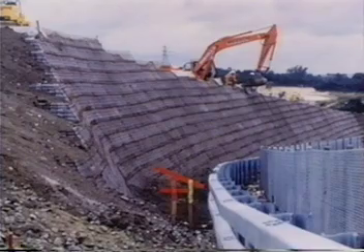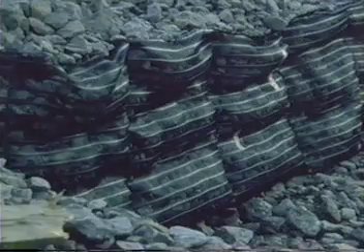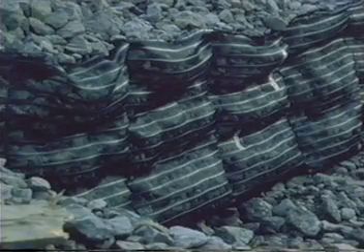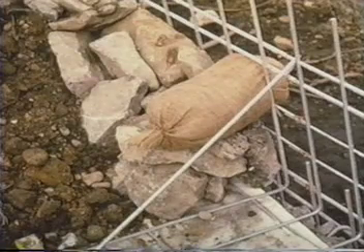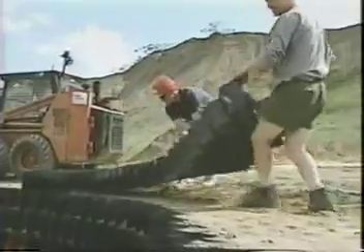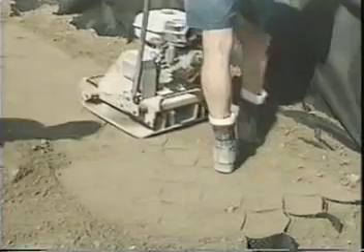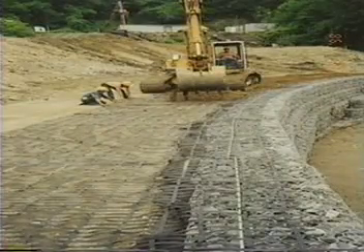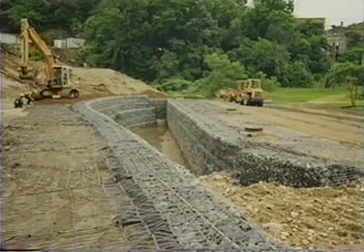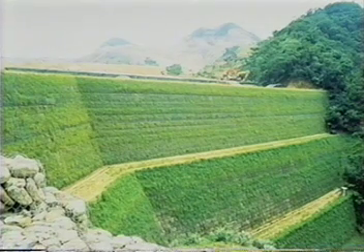Caged facings are formed as discrete units rather than as an extension of the main fill reinforcement. Examples include geomesh gabions, geobags, filled steel box cages, or geocells. In each case, the fill reinforcement is either attached to or entrapped between the facing units, which are progressively stepped. Here, a combination of gabions and geogrids is used for this newly constructed slope. The reinforcement greens over gradually as pre-seeded plants become firmly established.